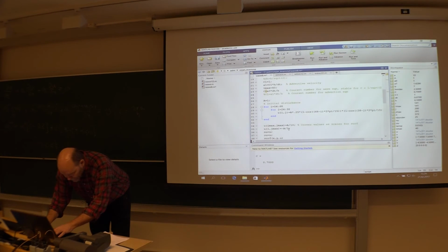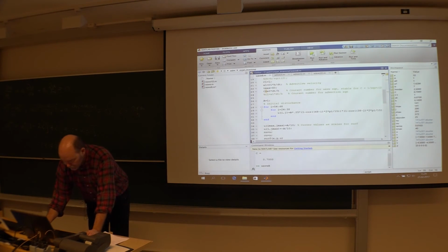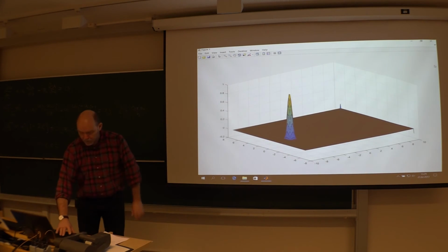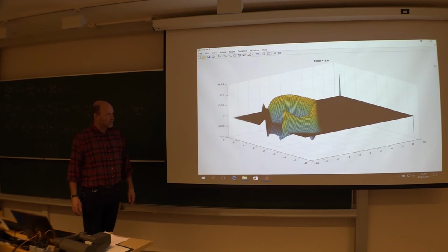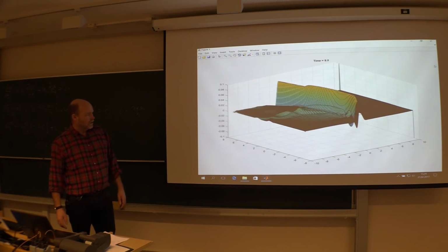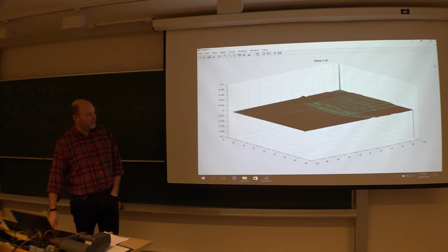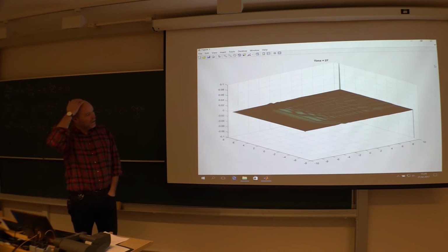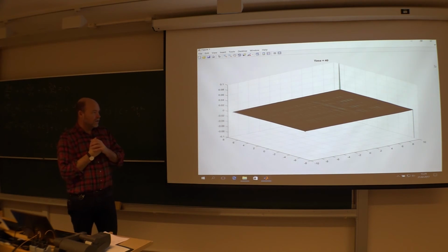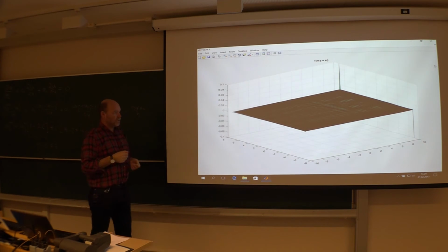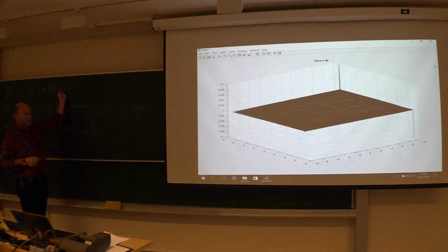Zoom in on the boundary zone by a factor of 10. A little jumpy at first. But then you see clearly it's not a perfect drain of the wave. And the reason, the problem, is the Courant numbers for the two different equations. To get the advection equation to be perfect, you demand a Courant number of 1. Then it will solve it following the characteristic curves.